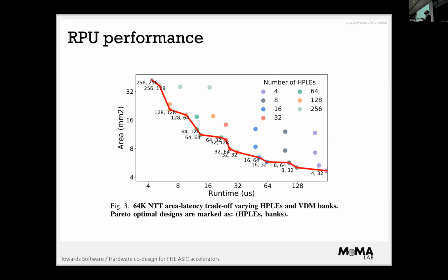The key switching matrix depends on whether you do RNS or not, and how much RNS you do. If you don't do RNS, the key switching matrix is actually very small. If you do 512-bit regular coefficients, you don't have many things. But everybody does RNS, so it makes the memory big. But if you don't do much RNS, there's a trade-off to be found on how much RNS makes you spend for what you get back. So we're currently exploring that, since it's ASIC, we can do 500-bit coefficients. Why do 32 bits?